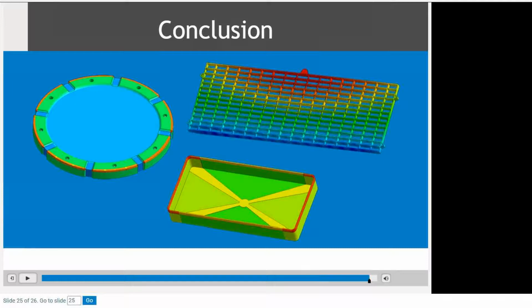Depending on the material viscosity, flow restrictors can have a huge impact or a small impact. The fill speed, therefore, could have a huge impact or a small impact. But if you really think about viscosity curves, the faster you inject, the lower the viscosity will be. However, if you're familiar with viscosity and temperature curves, this viscosity does change, but not in extreme measures. That's why it's important to really analyze the polymer material you are using to see the effect of fill speed on the ability to use flow restrictors. This is really important. That's exactly why we do what we do.